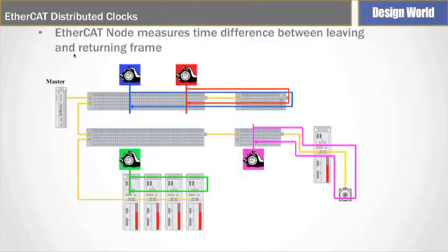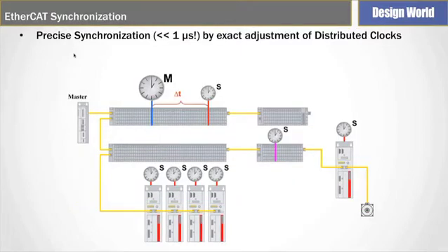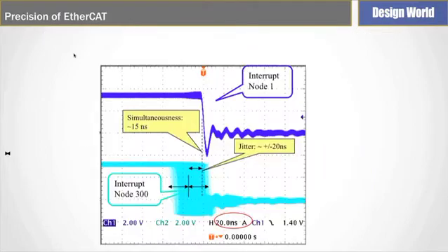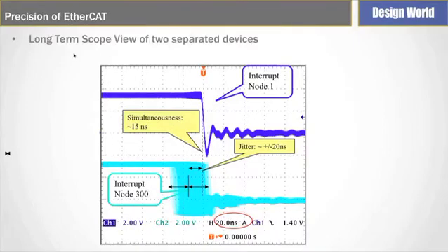This allows us very easily to synchronize the entire network to a 64-bit clock. A very simple phase lock loop instruction, which is just one small instruction, goes out that allows the slaves themselves to compare what they think the time is to what the actual system time is, and make corrections themselves through a drift compensation algorithm. So this allows us to synchronize the network not to the millisecond and not to the microsecond, but actually down into the nanosecond range.